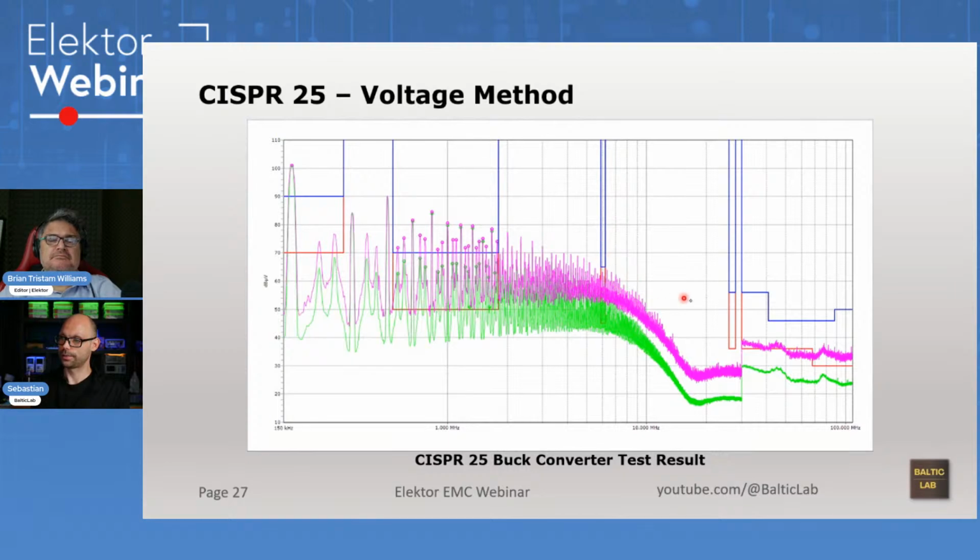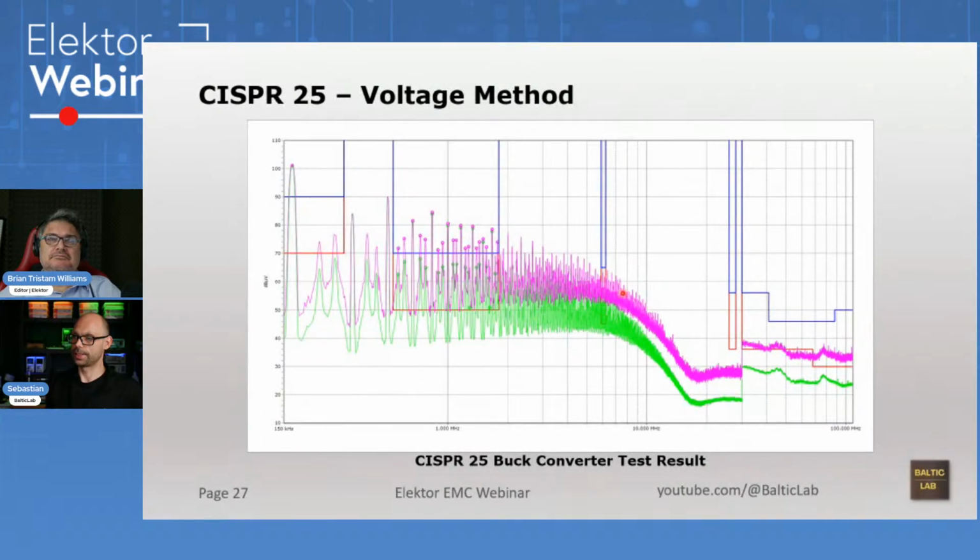There's also another line that you could draw. This line up here has about 20 decibels per decade of attenuation, and down here we should be at around 40 dB per decade. This corner point right here has a reason why it's there.